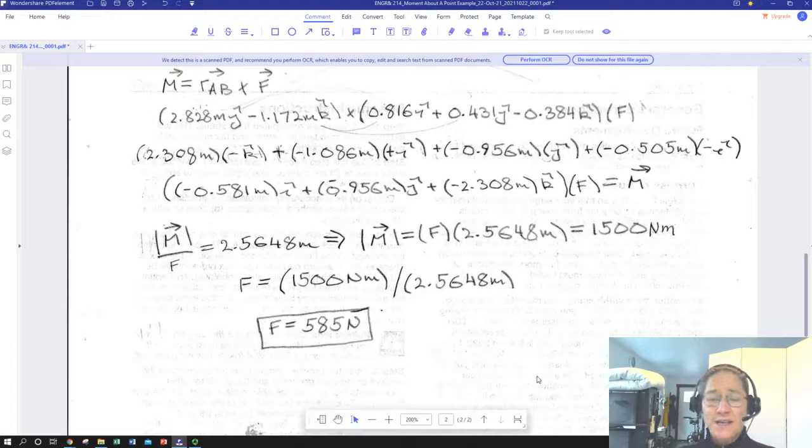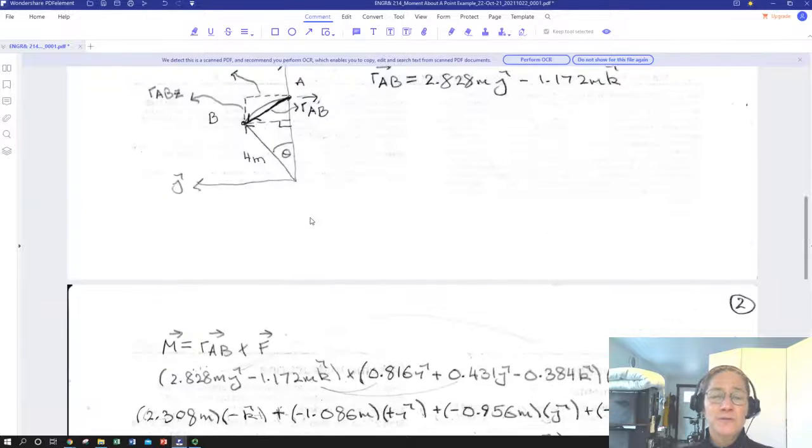So key concepts: lots of use of vector magnitudes to relate what we didn't know to what we needed to know. We got to execute our cross product to actually calculate the vector moment from the radius from the point of interest to the point of application of the force, and an actual force vector.